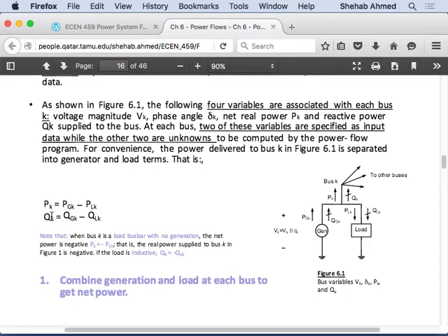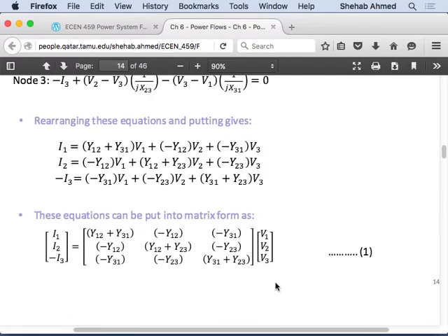The system, right? I have inductors, I have loads, I have resistors, I have power factor correction. So there will be a bus, or buses sometimes in a power system, with a generator on it, where I know its voltage as a magnitude and an angle. And I will use that as a reference, right? That's the mathematical anomaly that we also dealt with in the inversion of the matrix. In inverting this matrix, I said it's singular, but if I know a certain voltage as a magnitude and an angle, I've solved it, right? And we actually have that physically happening.